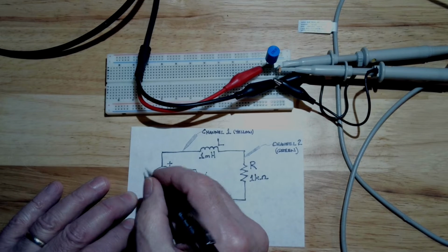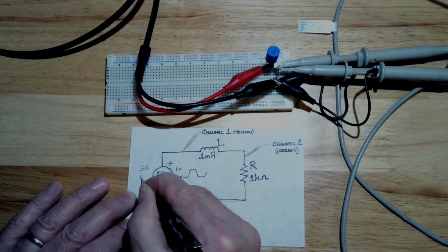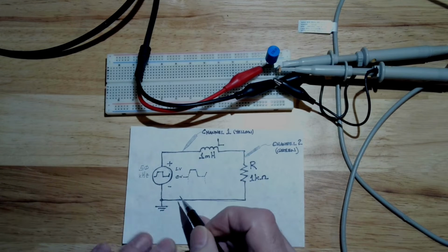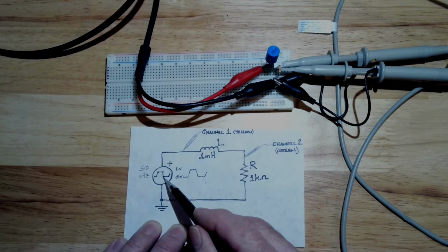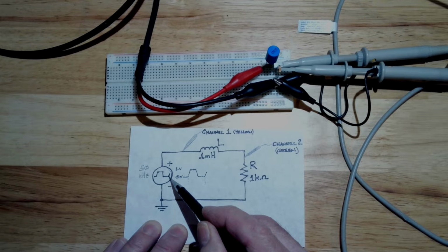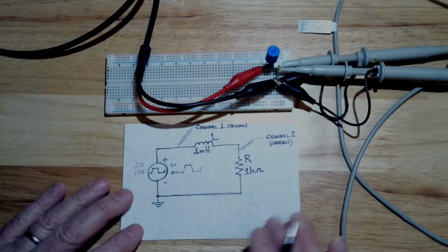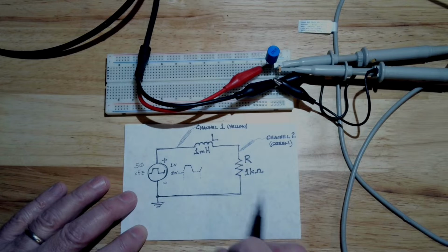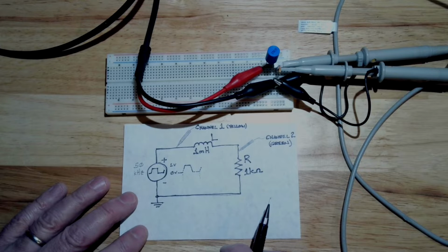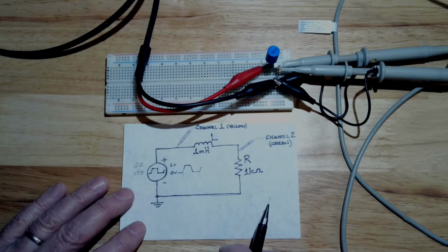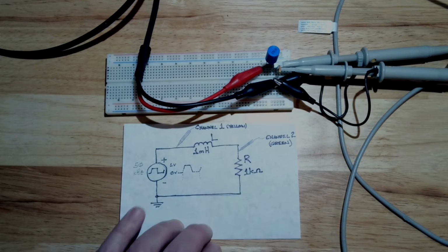This guy is 50, and I'm using my pencil now, it's been hard to see, but 50 kilohertz. That means there's 50,000, that's the K, 50,000 of these where you go up for half the time and down for half the time. 50,000 of those cycles every second, okay? And if there's 50,000 of those every second, then each of those has a period of 20 microseconds, okay? Meaning the time from here to here is 20 microseconds.